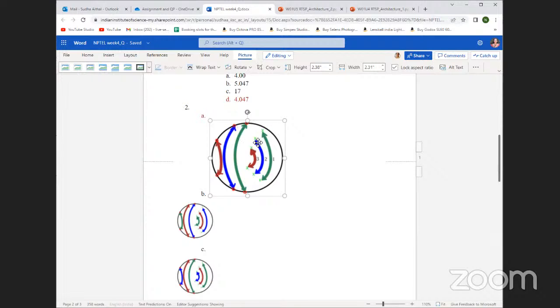The next one will be the next farthest, combined with the next nearer zero, and the last one is last because it is a 6th order filter. Sorry, 6 into 2, a 12th order. Basically, each is a 2nd order section because you will have 2 poles and 2 zeros in each section.